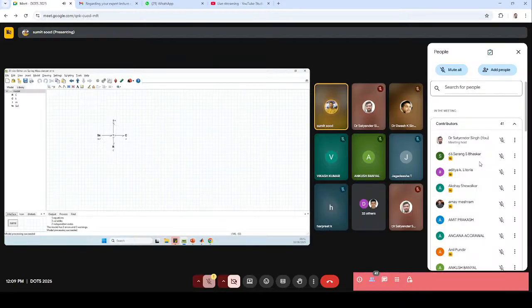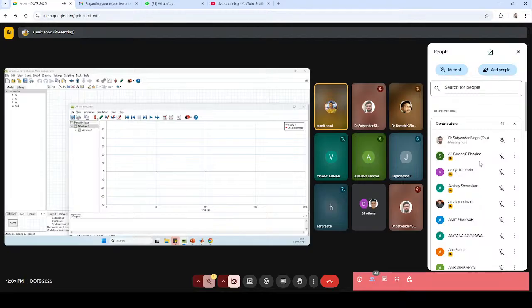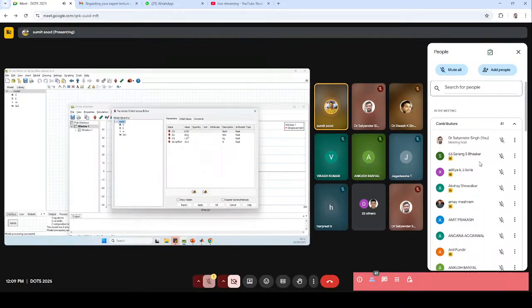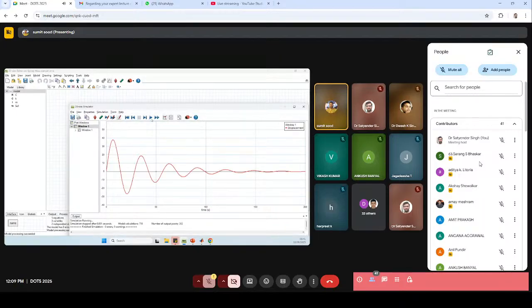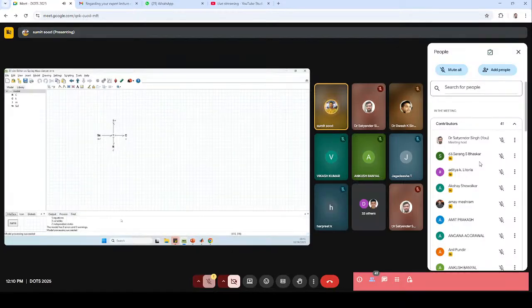And in order to simulate the system, you see here these are the different values that we have seen for the different elements. If we simulate the system, you can see that the system oscillates like this. This represents the displacement, and you see that the displacement keeps reducing because of the damping effect, and in the end the system will eventually come to rest. The same thing we can also do with the help of MATLAB Simulink, like I showed you.